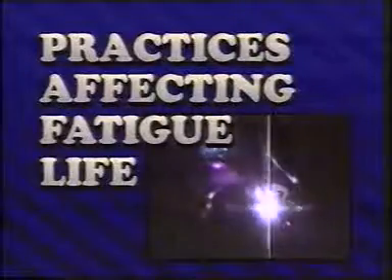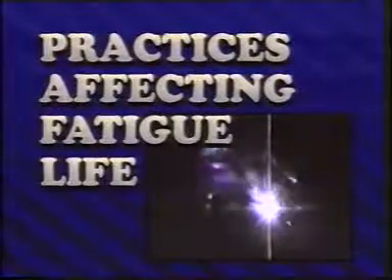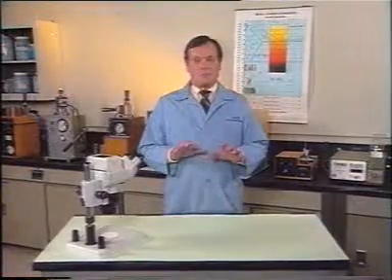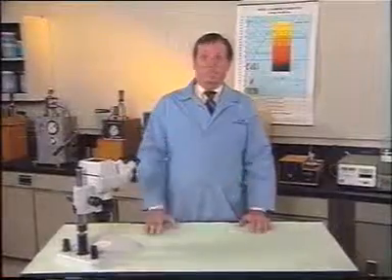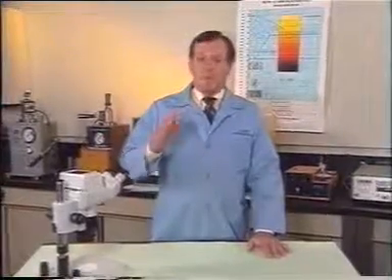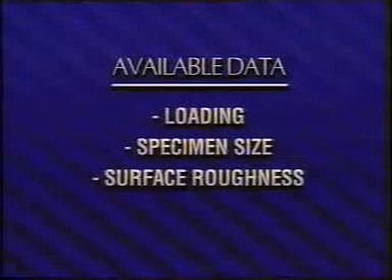Practices affecting fatigue life. With so much diversity in function, loads, stresses, materials, and environments, simple rules for fatigue-resistant design cannot be stated. However, a number of useful practices can be defined. When applied with good engineering judgment, these practices can reduce significantly the probability of fatigue failure. The available data are normally shown for a specific type of loading, specimen size, and surface roughness.